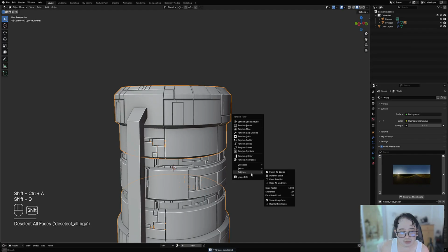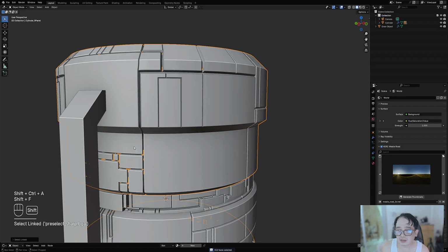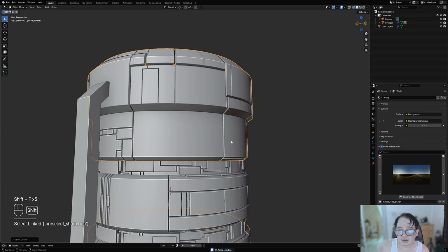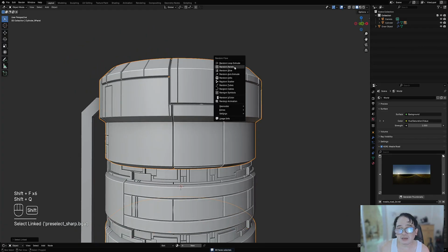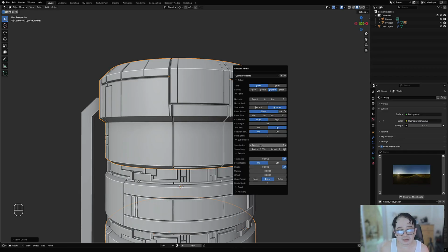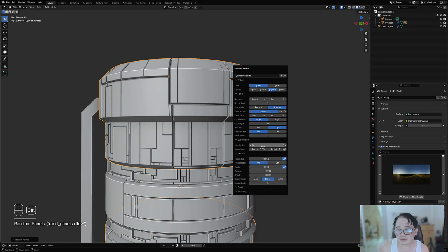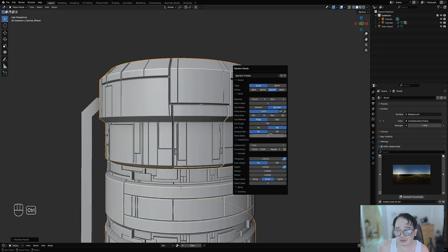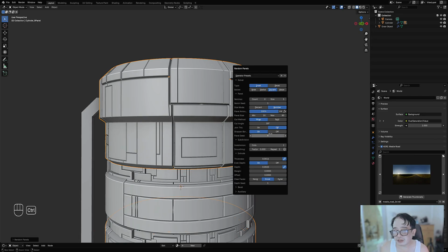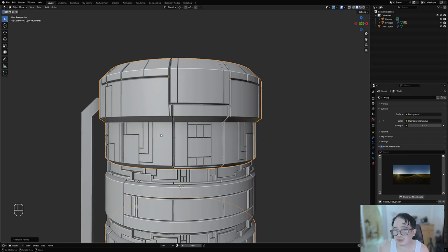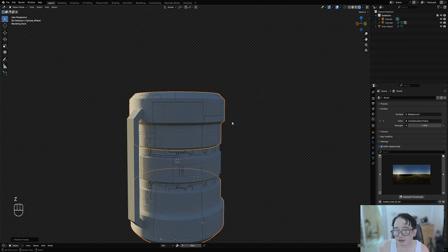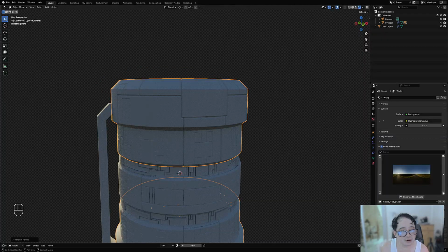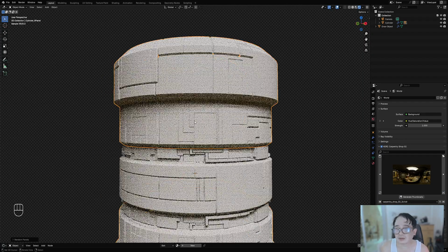going to also go to the settings of random flow and click on this clear selection. So every time we use randomization, the selection is automatically cleared out. So we can then use pre-select to select new areas again without having to use the deselect all feature or manually deselecting all the faces that you have selected after. Okay, why am I still on the same? Okay, there we go.